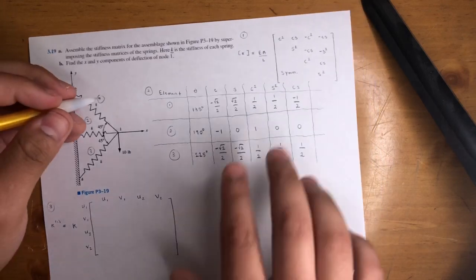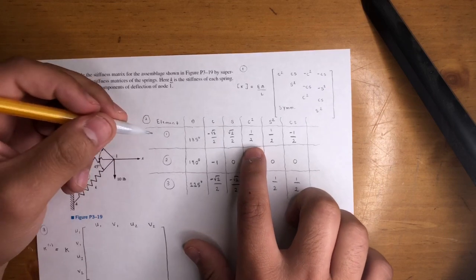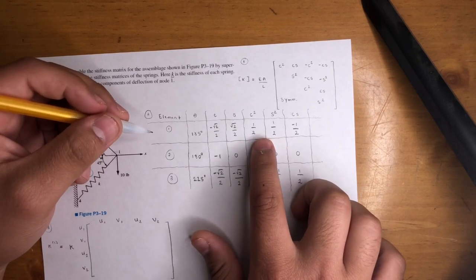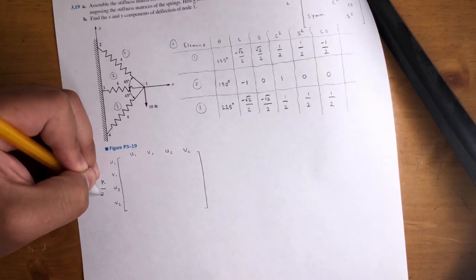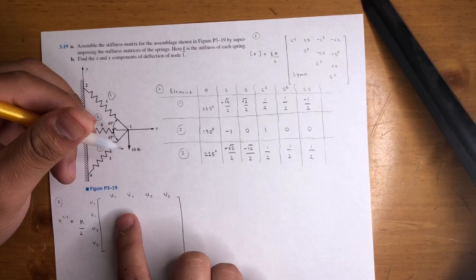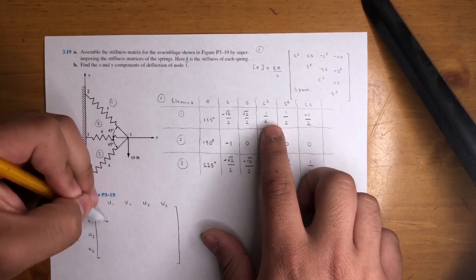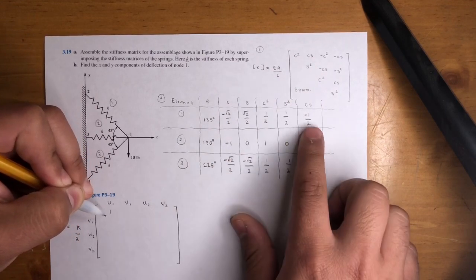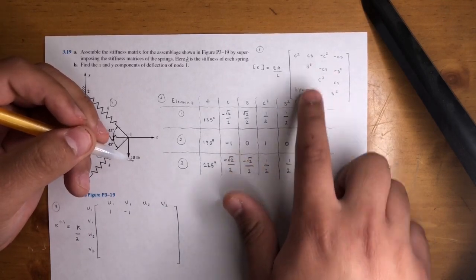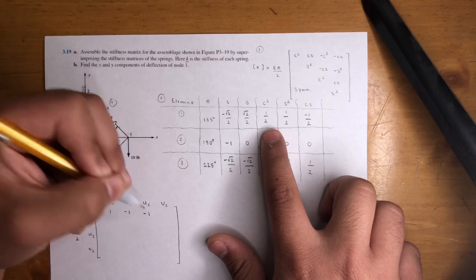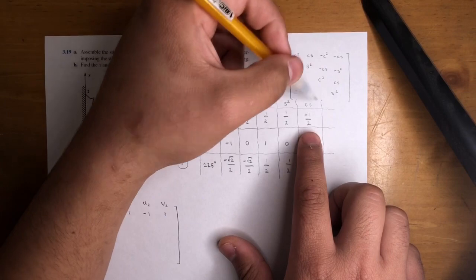All right. So for the first one, it's cosine squared. Again, we're on the first element, so it's half, okay? But I'm going to factor out that half, so it could just be 1. So I'm going to divide K over 2. Now everything's going to be nice, just ones, because everything up here is ones, right? It would have been half, but we factored out the half, so that's just 1. C times S is negative right there, -1. Again, we factored out the 2. Negative C squared, it's -1. And then negative CS, that will be a positive 1. Again, the negatives cancel out.